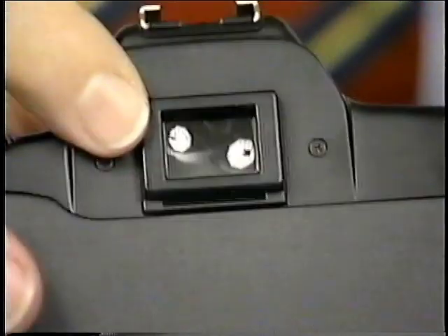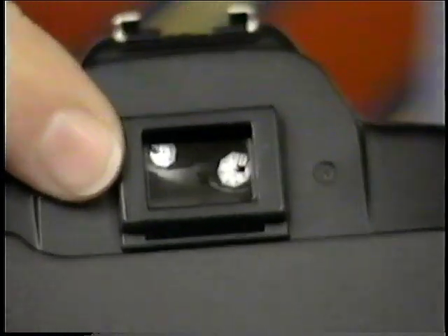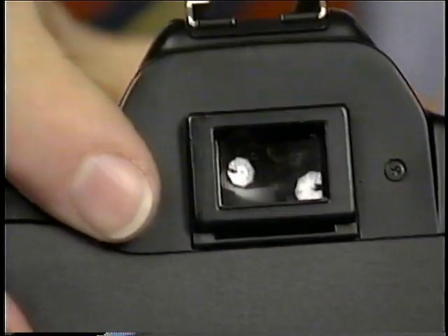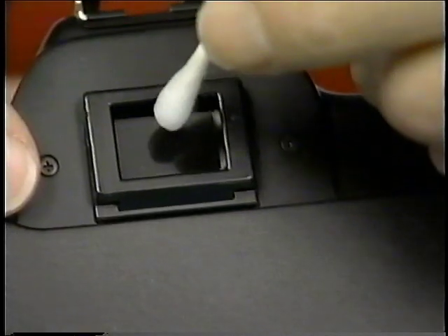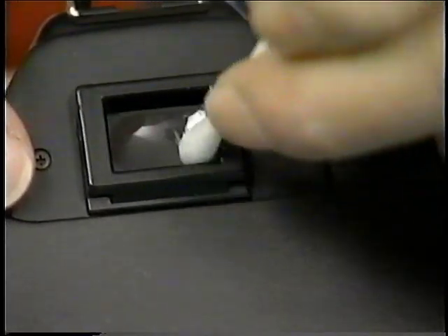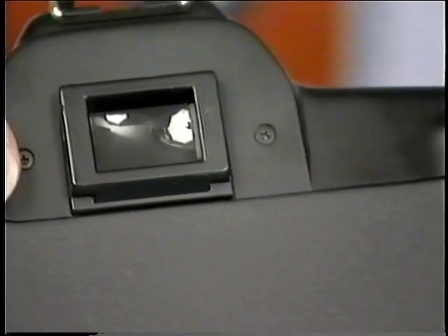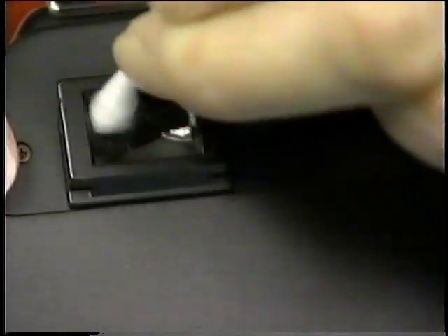One of the most important lenses on the camera is the eye lens. They're almost always dirty. You get face oil from eyelashes and so on against them. Also, they're great accumulators of dust and dirt. So you'll want to clean those, and again you can use a damp cotton swab, then a dry one. Move in again, working to the edges and getting all the corners cleaned out. The customer will really appreciate this because that's going to brighten the viewfinder a great deal.